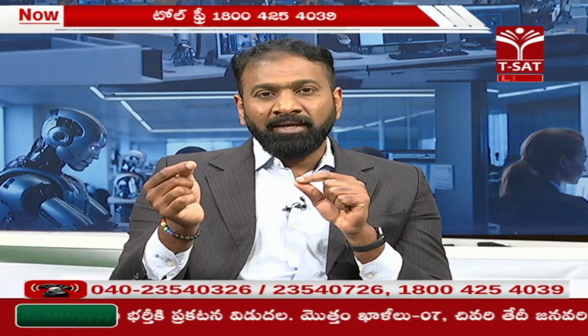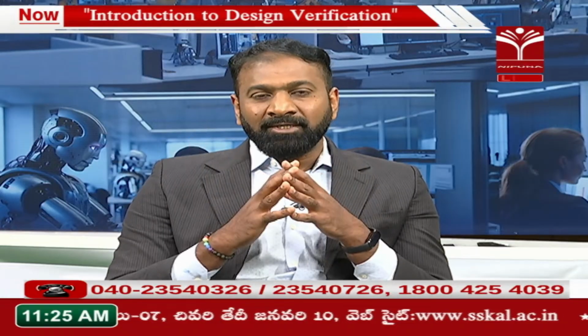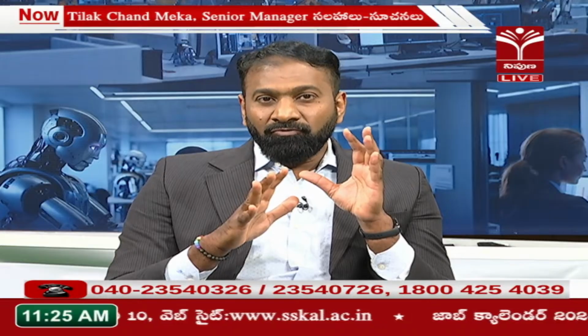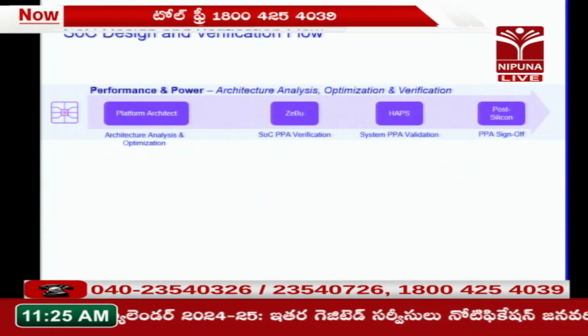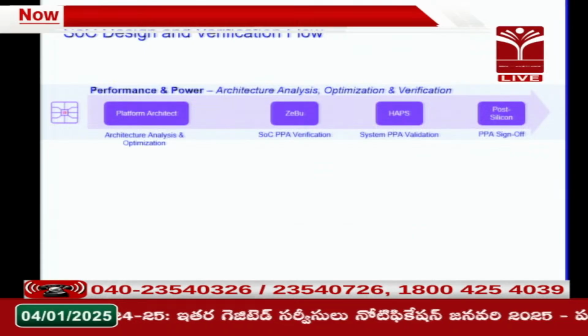We want power to be less than, let us say, 70 milliwatts. We want performance to be, maybe the clock frequency should be 1.2 gigahertz. Area of the die should be less than, maybe, 1.2 millimeter square. That's my requirement here, and based on this requirement the entire process flow comes in. Now if I have to validate this mobile SoC right up front, how can I do it? That is what this SoC level design and verification flow helps one to achieve.